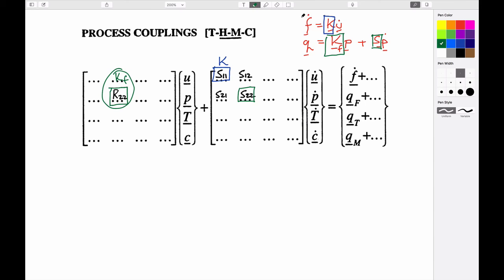And of course, what we've referred to as the load vectors, the parts here, would be these parts. And these would be the variables that they operate on. They only operate on these first two components, pressures and displacements. And so that would be our two individual systems that have no communication with each other. If we want to make them talk to each other, in other words, we want the fluid pressure changes in one system to give some impact on the solid mechanics expression, then we need this term.